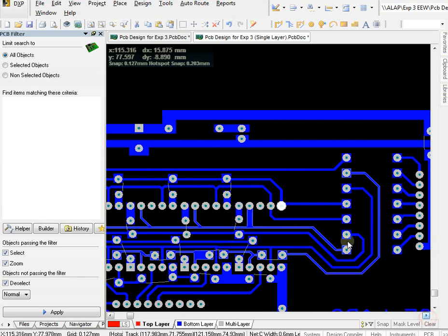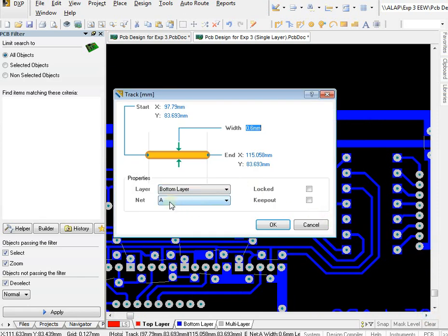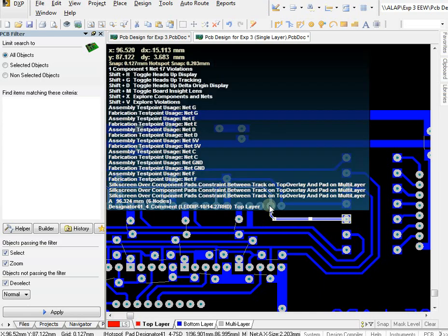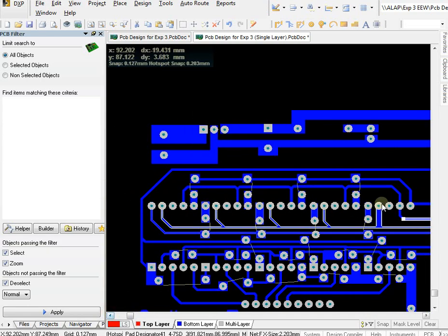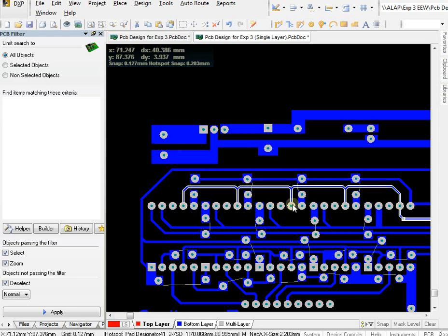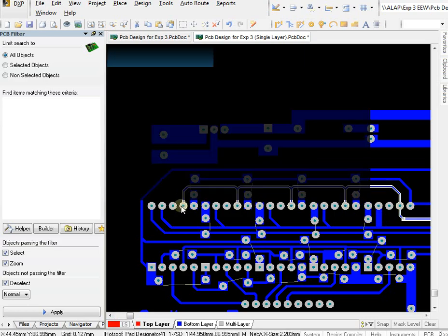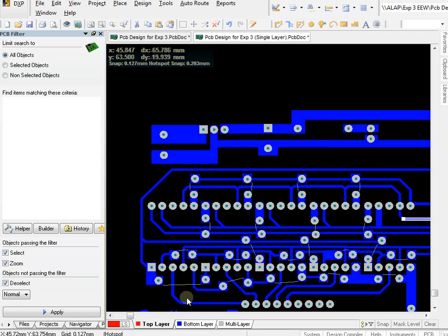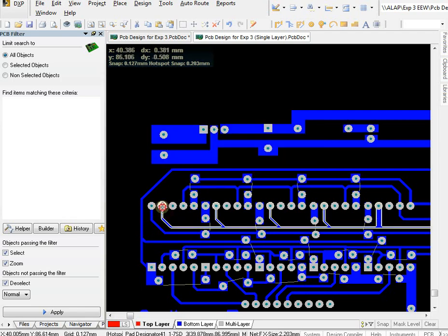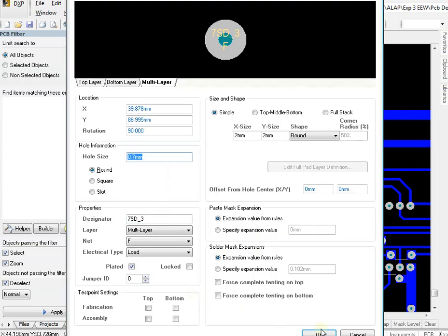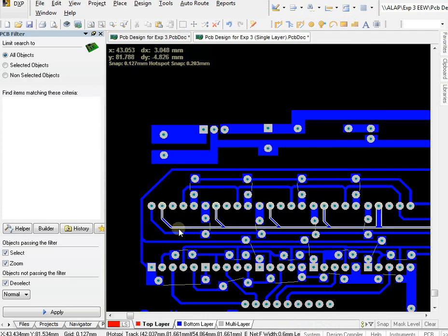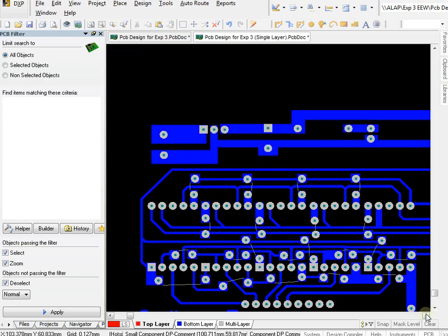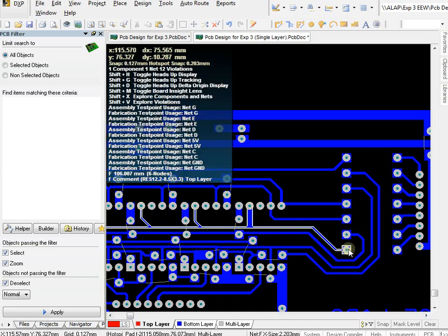And then if you see the next wire, which one is this one, that is A. So you can see A is connected with this segment, and then one wire can straight away go, because this is connected directly, this is connected directly, this is connected directly, this is connected directly. Then the third pin or the center pin over there, it's common cathode, no need of connecting it, I am connecting it with the below pin. So then the next pin, you can see over here, this one is which one? Let me just check. This one is F. So you can see this one is F, F is connected directly, and from this F, this is going towards F over here.